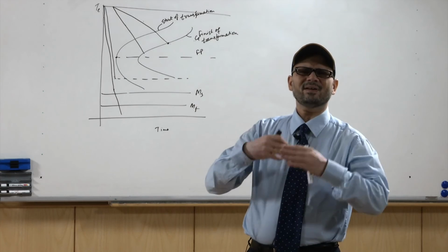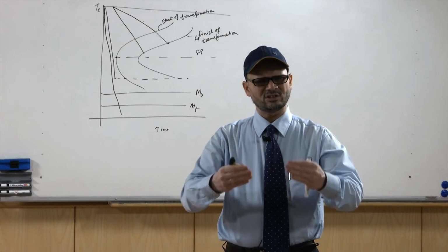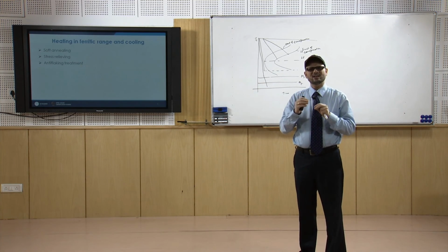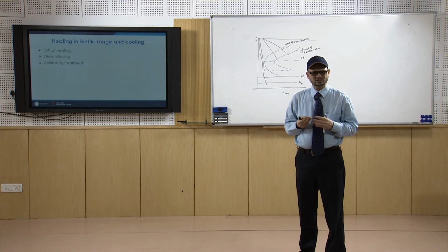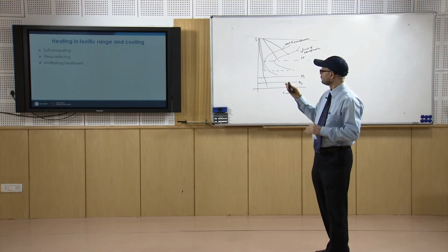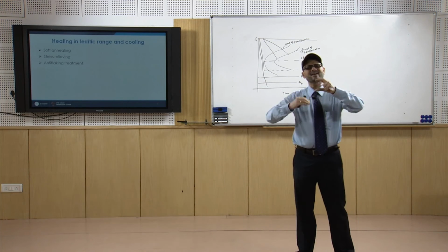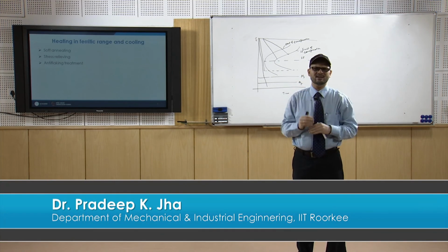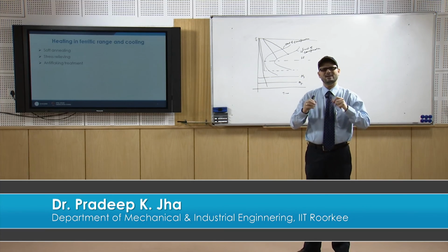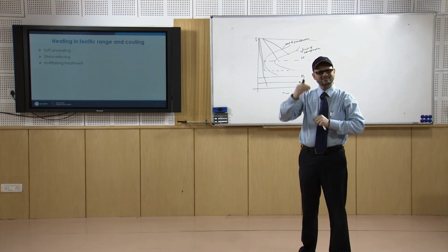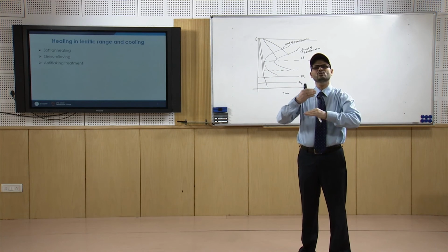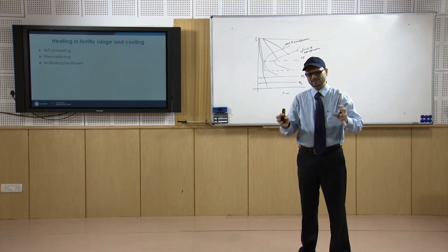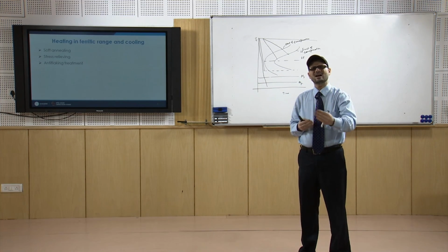So, you have different kinds of heat treatments for these steels, and these heat treatment processes induce different kinds of material properties. You might have treatments like hardness to the skin. So, you have surface hardening, with many methods like flame hardening, carburizing, and nitriding. Different kinds of surface hardening are carried out many a time. If you feel that the core should be soft and only the surface should be hard, you can go for these surface hardening methods.